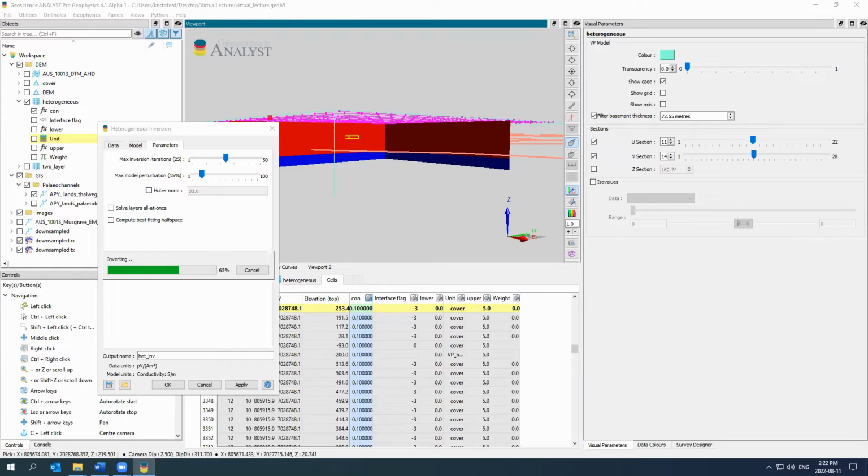Well, there is a question in the meantime. Can I verbally repeat how to get to the uncertainty assignment GUI? Sure. So the uncertainties for EM data are under the contextual menu of your EM data. So you can right click on your receiver. You'll go to create, because you're going to create EM based uncertainties or channel based uncertainties. And what that will do is allow you to create those uncertainties per channel all at once.